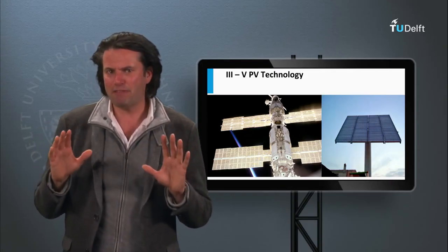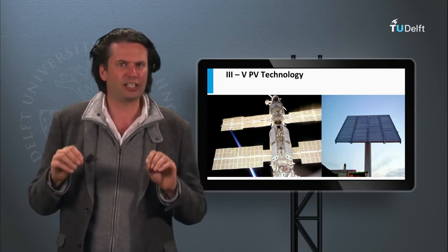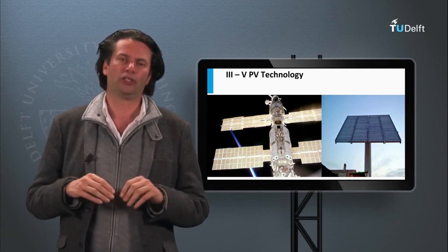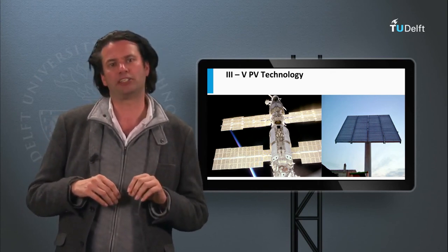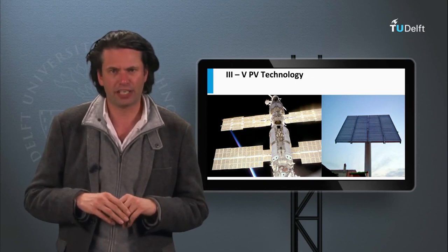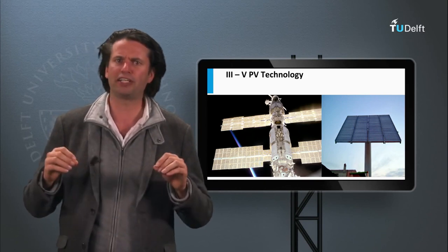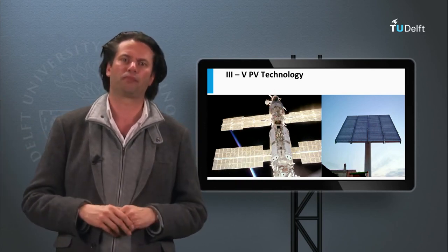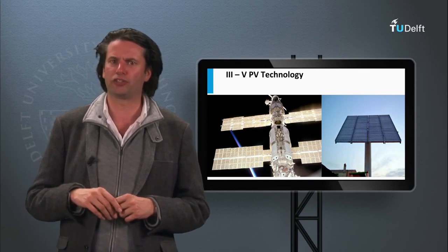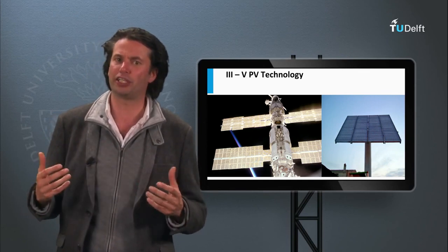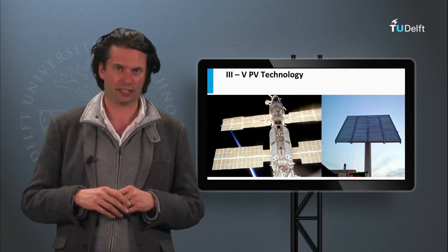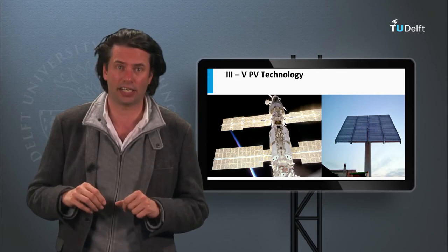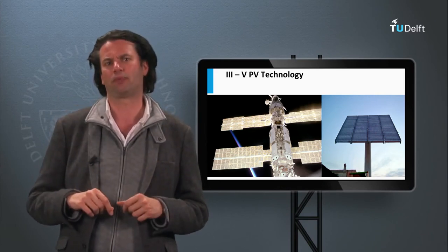As the III-V PV technologies are expensive, they are used for space applications and in concentrator technology. The dollar per watt peak of a small expensive III-V multi-junction device can be improved by concentrating the irradiance of a large area on the small solar cell device. An advantage of concentrating sunlight is that the open circuit voltage is increased with irradiance as well, as long as Auger recombination of light-excited charge carriers does not become dominant.